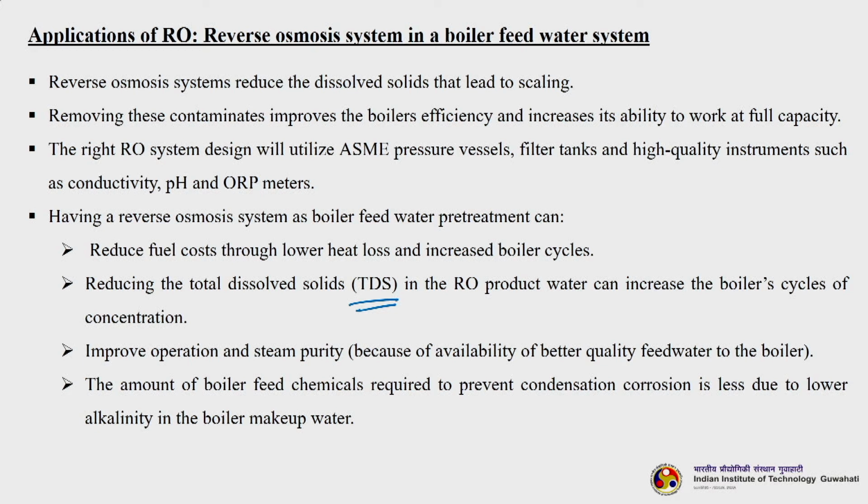So, it improves operation and steam purity because of the availability of better quality feed water to the boiler. So, the quality of steam becomes very good actually. The amount of boiler feed chemicals required to prevent condensate corrosion is less due to lower alkalinity in the boiler makeup water.